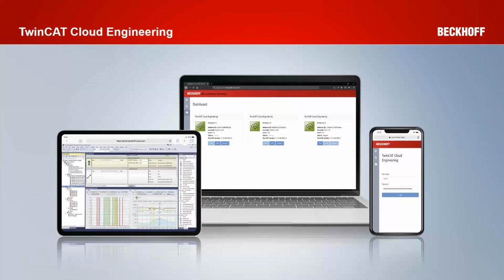So this is how it looks. This is how the dashboard looks when you log in with your user credentials to the TwinCAT Cloud Engineering environment. Like I said, you have an overview of all the TwinCAT Cloud Engineering instances. You can interact with the instances. You can start them, stop them, see metadata of the instance, which means in which data center the instance is running, which TwinCAT version is installed in the instance, and you can also connect to the instance.